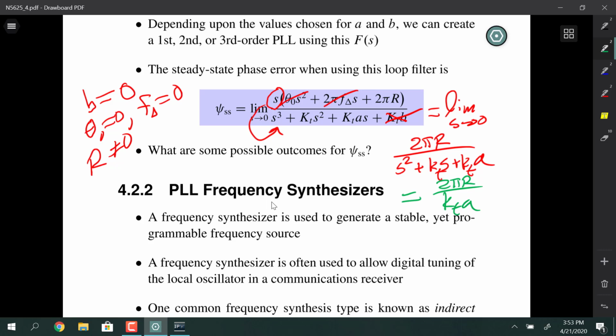So there's going to be a large phase error if you're trying to track it with a second order loop. As it comes close, it's going to be building up the error, and then it's going to hit the peak when it flies overhead, and this bounds then the static phase error, or the steady state phase error. If you wanted to be able to track that system without any errors, then you'd have to go to the next higher order loop. On the other hand, if we were to just see what a first order loop would do, if we went with a first order loop, it can't track anything but a phase step with 0 error.